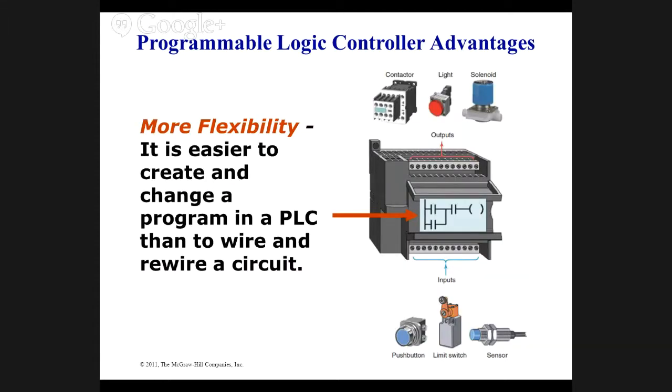More flexibility. Well, let me tell you something. A PLC you can rewire on the fly. And what I mean by that is you can change the program while they're running, if you're careful, and change how things work. So let's just say that we had a photo eye on a line, and we can use markers even though that won't go online. That's okay.